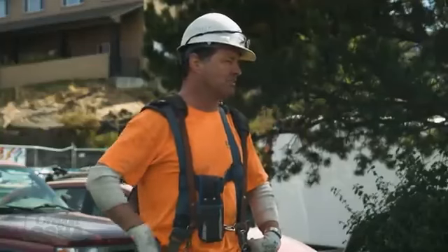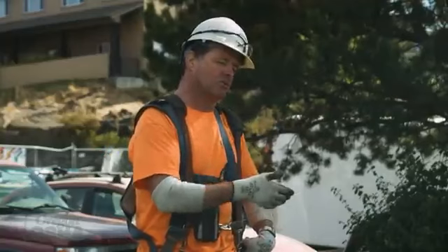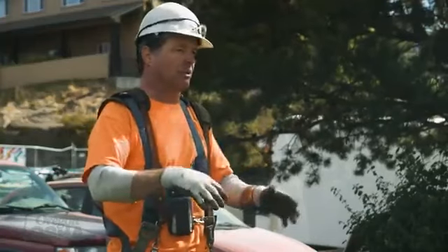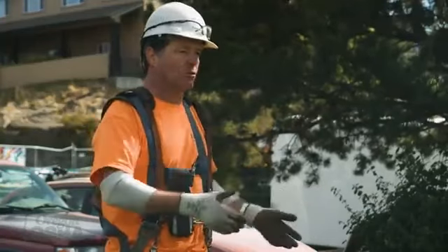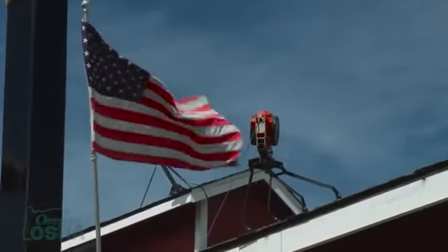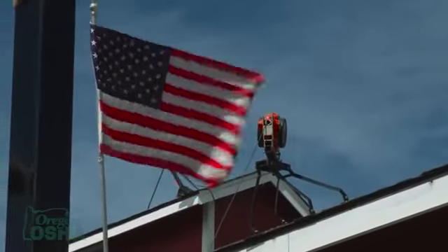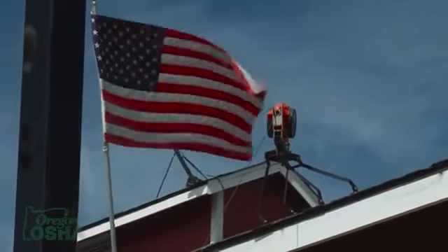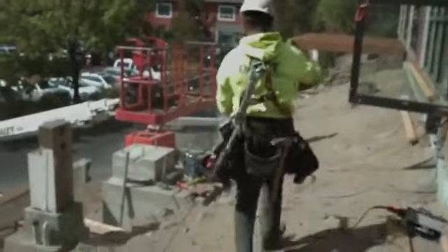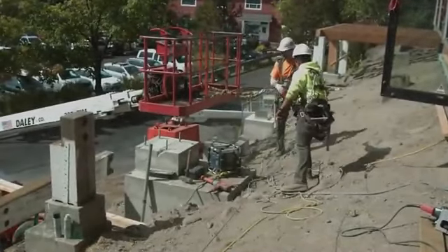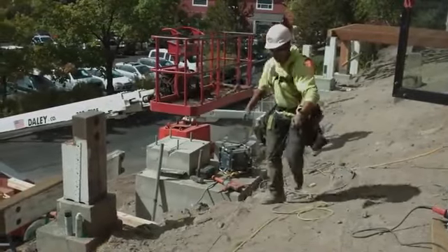But if you hit resistance as you're driving the nail in, or we use screws, then you know your roof mount is attached properly. And I call it a roof mount, but in this context, it would be a floor mount. But it's elevated, like a gun turret, and it just rotates 360 degrees so that the retractable yo-yo, or whatever you want to call it, is facing you. And every time you walk, it's paying out your fall protection. And as you walk back, it'll suck it back in.